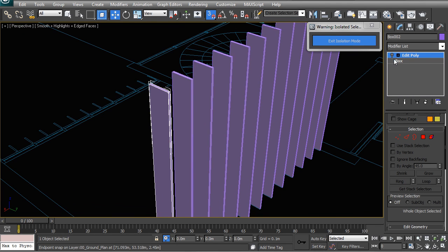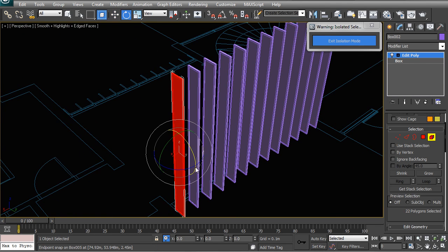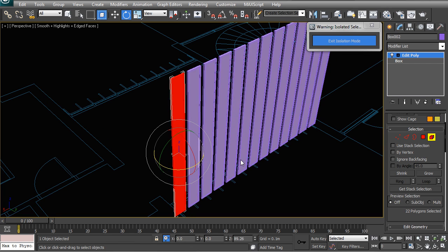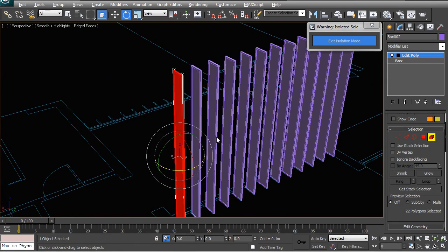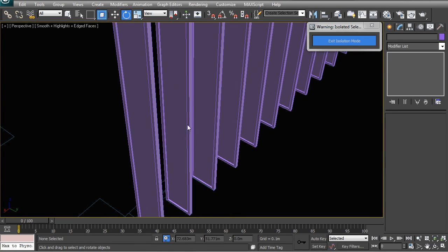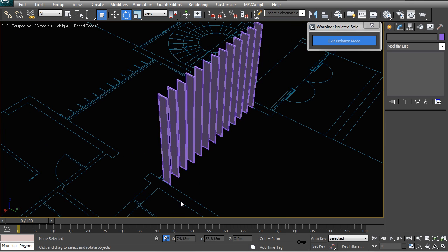The other beautiful thing about this is that if you want to animate your screens, you could take one of those screens and you could turn it, for example, so you could show your client what they would look like if they're all closed, and you could animate that without any problem. So it really does give you quite a lot of flexibility. If you do, however, start having a whole lot of little joints, pins, rotating devices, etc., just remember to group each one of them and instance it across so that you do have a neater assembly to work with so that you don't have too many objects.